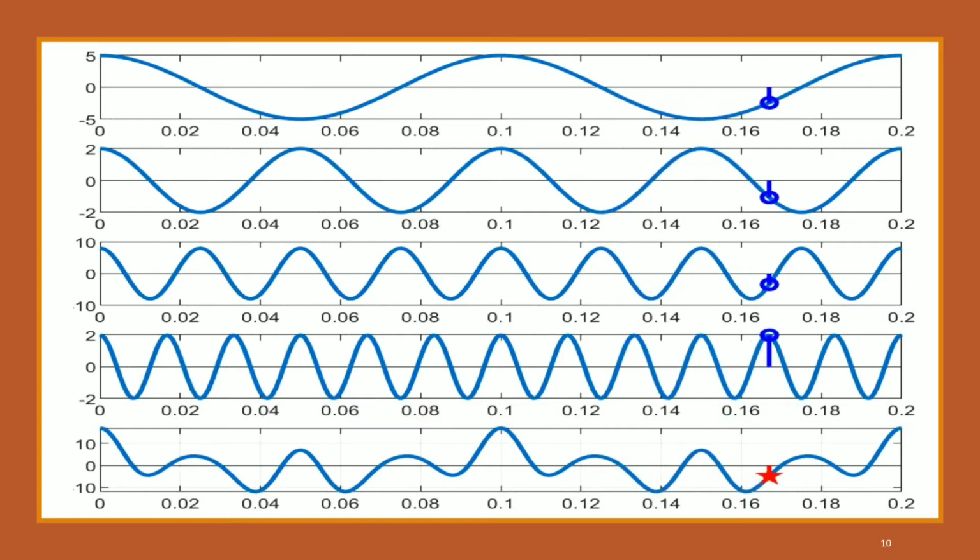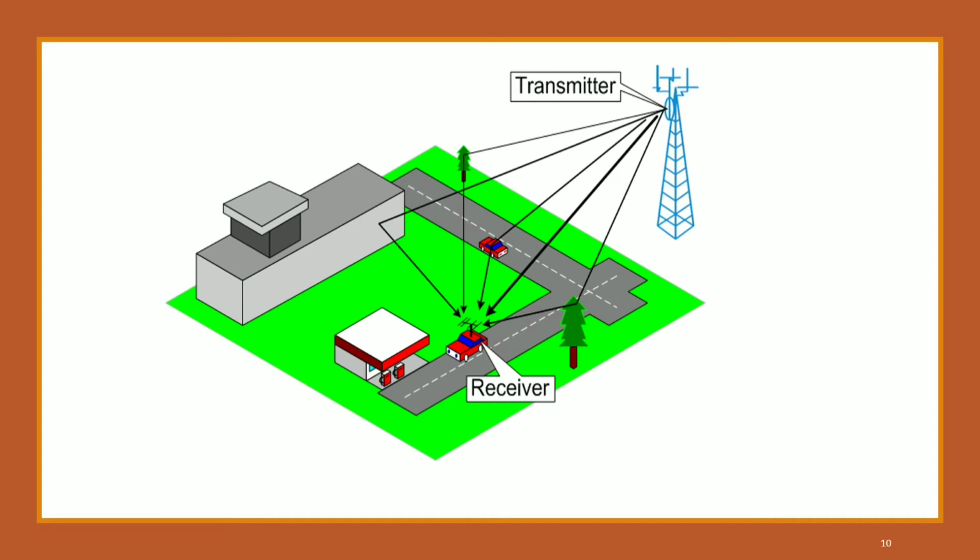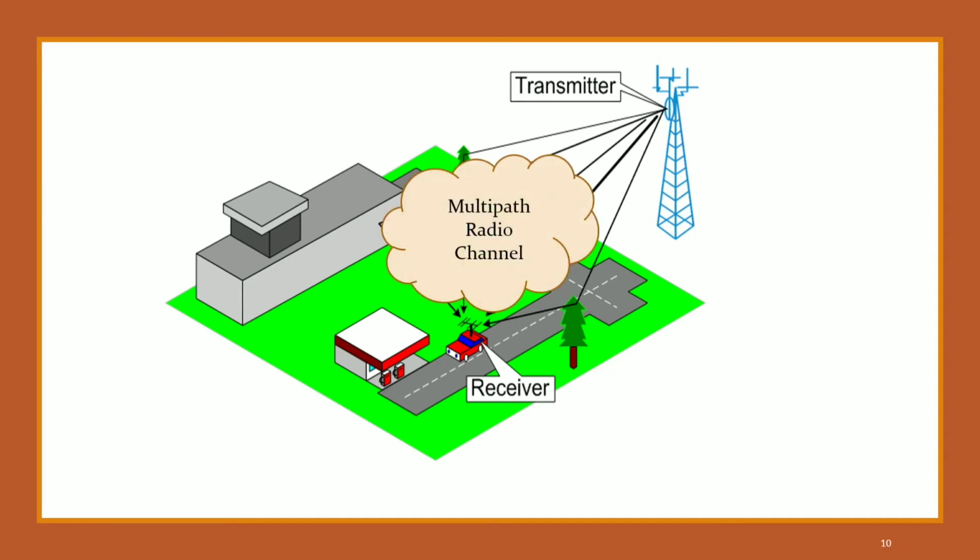As a comment, one can apply different phase shifts and amplitudes while keeping all the signals of the same frequency. This would simulate a communication scenario where the same signal is received through direct and reflected paths. The phase shift would simulate the path delays, while the random amplitudes would simulate the losses in the paths where reflections and absorption occur. The composite signal would be a distorted version of the original signal.